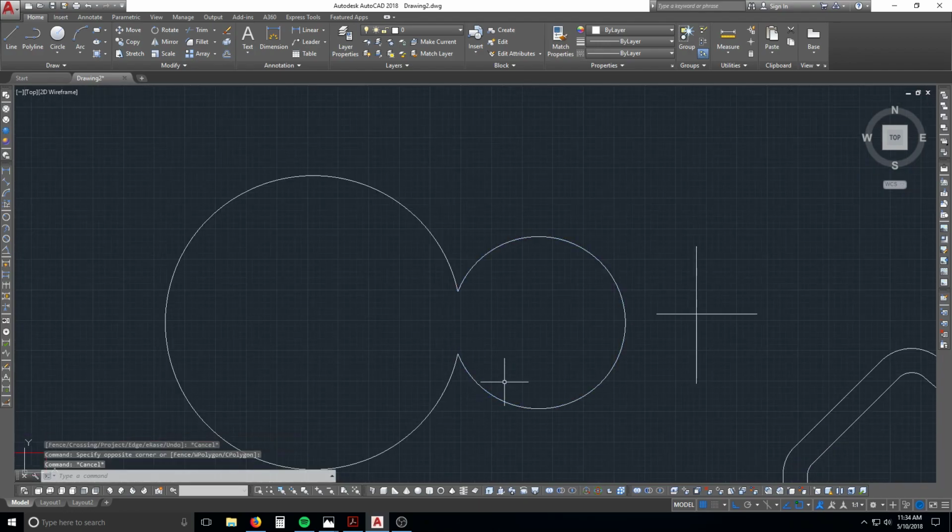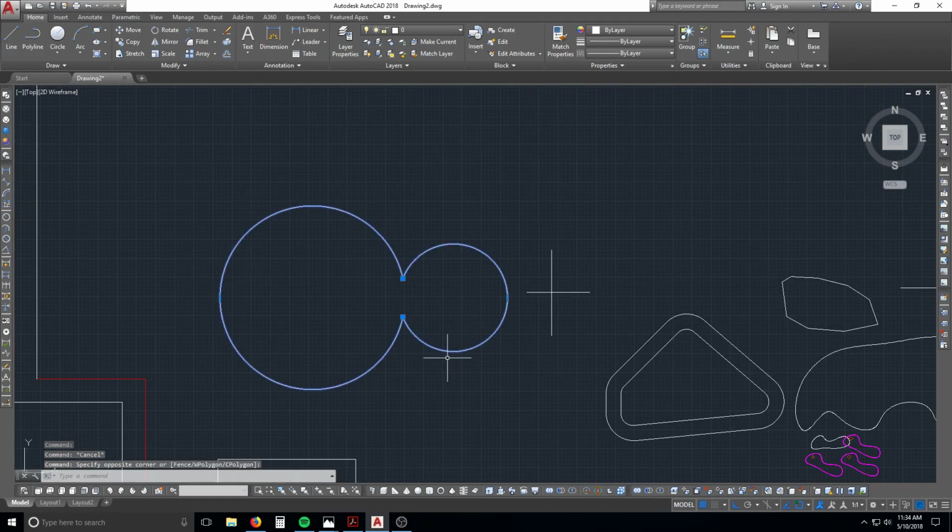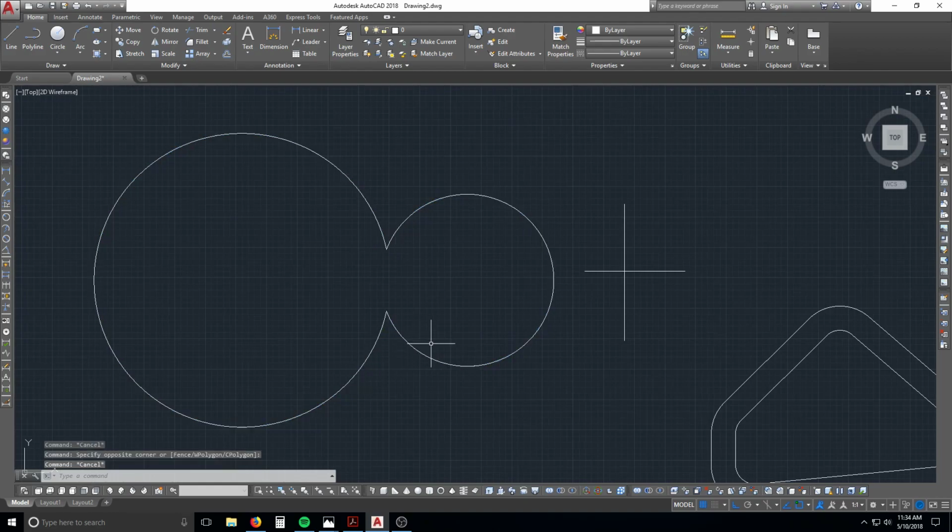There is another cool thing to join these. You can join that one to that one. See how now, when I was telling you, you can't explode circles? This is one of those instances where you can, because it's 2 separate circle entities joined together. So now you can explode, X, and there you go. You're back to where we started, we kind of went in a circle there, no pun intended. So that was the join command, the trim command, and the break command, right there together.